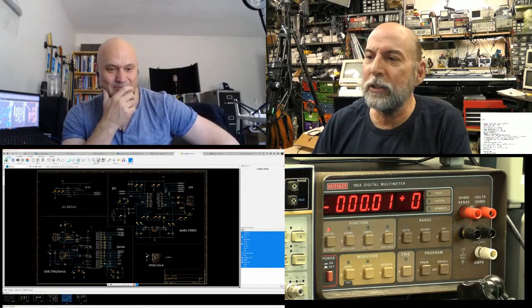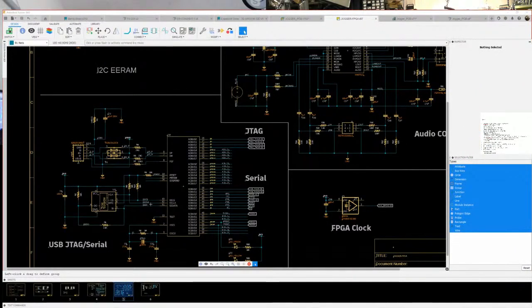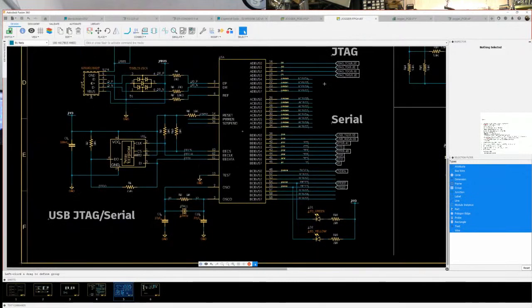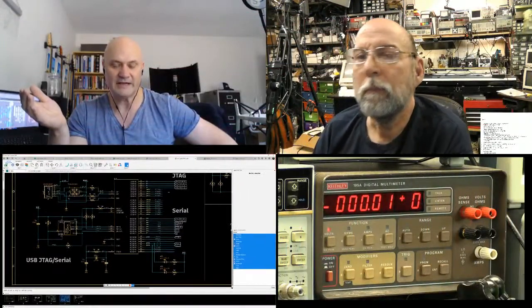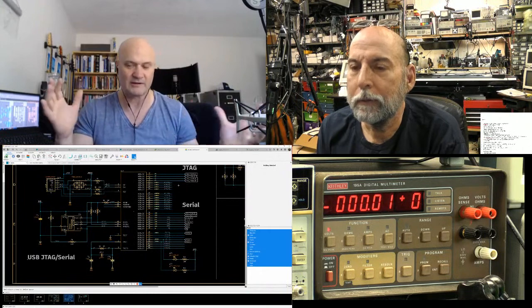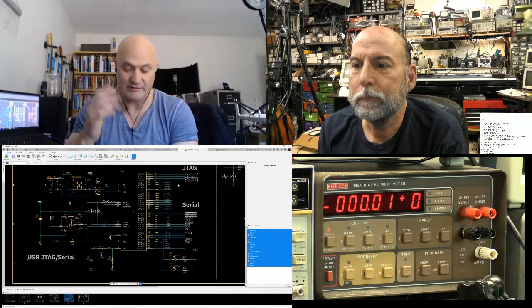Right. Yeah. So back to what you're showing us here. Is this the schematic for what you've been talking about? Yeah. So I think I showed this one other time. This section here is my JTAG, and what I love about these FT2232s, the Universal Serial and JTAG chip from FTDI, is that if I'm just having one JTAG chain, I can have that on one side, and the other side can still be a virtual COM port, which is really useful for the ESP32 because the ESP32 can boot off of that. I can download code to it using the normal serial connection that the bootloader uses, and it's also a serial interface over USB after the whole board's brought up and is running whatever program. I've got a USB connection to a host to download other programs or interact with it in whatever way I want.